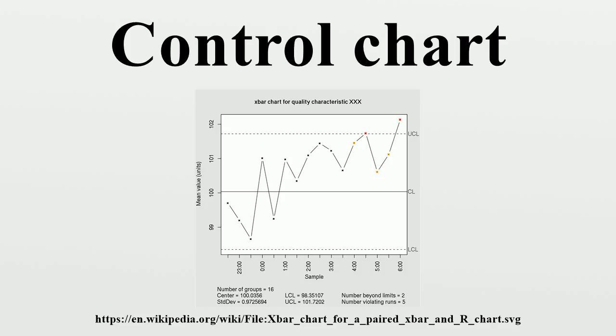Process capability studies do examine the relationship between the natural process limits and specifications. However, the purpose of control charts is to allow simple detection of events that are indicative of actual process change. This simple decision can be difficult where the process characteristic is continuously varying. The control chart provides statistically objective criteria of change. When change is detected and considered good, its cause should be identified and possibly become the new way of working. Where the change is bad, then its cause should be identified and eliminated.